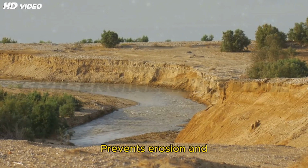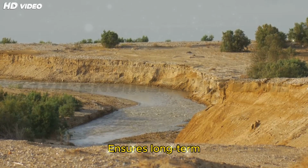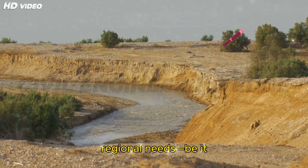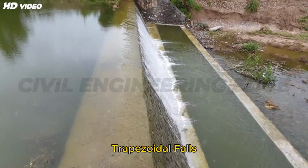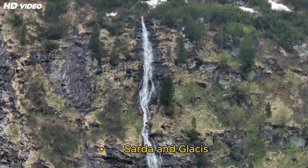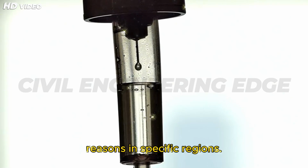Benefits: prevents erosion and structural damage, improves water distribution across varying terrain, ensures long-term safety and durability, and adapts to regional needs, be it Punjab's plains or Maharashtra's hills. Cost efficiency: simple vertical and trapezoidal falls cost the least and require minimal upkeep. Sarda and glacis falls offer a balance of cost and performance. Baffle and siphon drops are costlier but necessary for technical and safety reasons in specific regions.